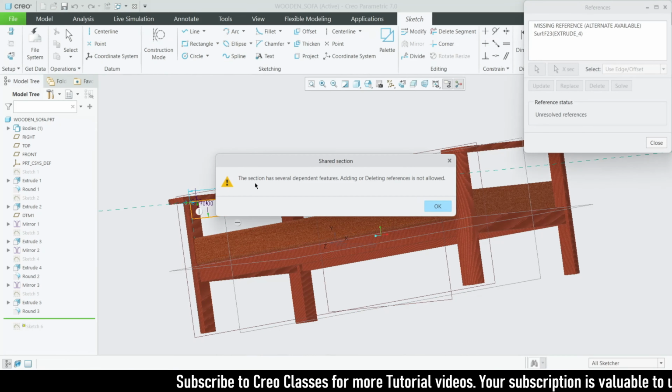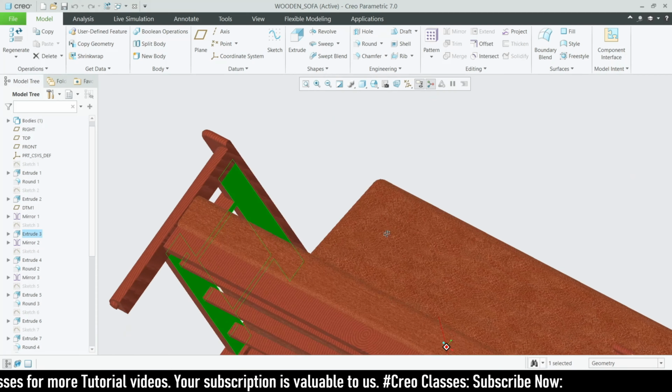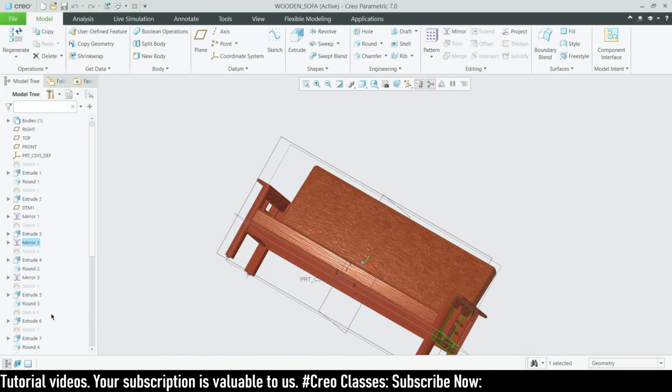Yes, on this face I have started my sketch. Here I have drawn a rectangle with a height of 70, like the same frame, this is also 70. So from this face it will be 70. Now we have to extrude that. The extrude length will be the same, so we have to use the same width as the lower arm. This will be 35, so 35 by 70. You have to draw this rectangle where I have left.